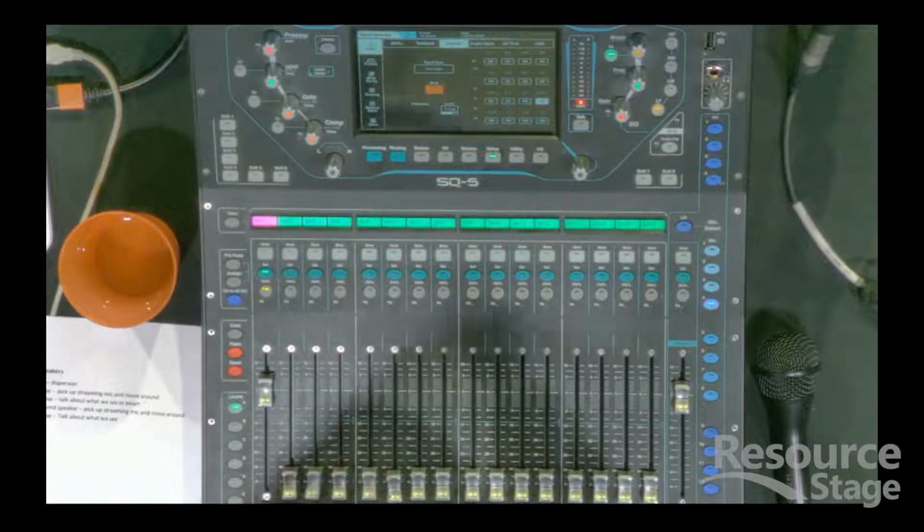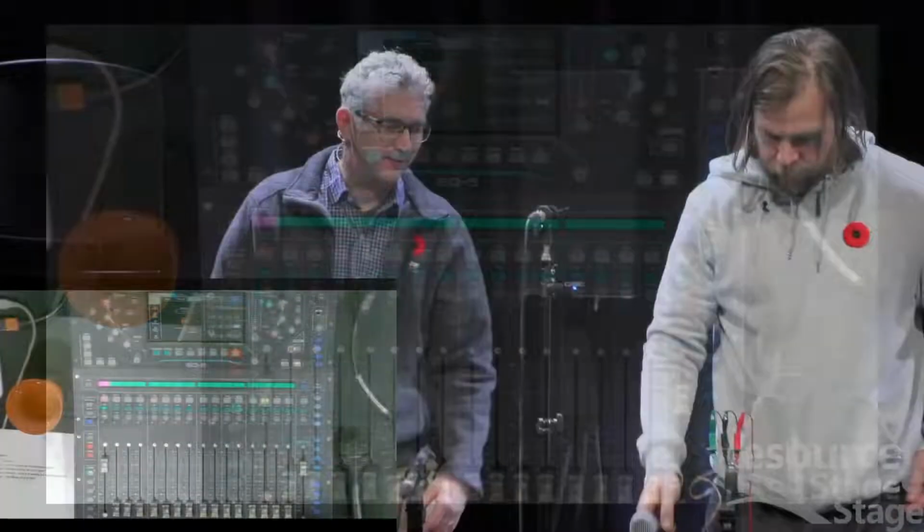So it's important to have the faders operated at or around the 0 mark, so that you've got the most control. You can move the fader a little bit and get a little bit of volume control. If the faders are down halfway, if you've got your gain up too high and your faders are down quite a ways, you move the fader a little bit and it's going to affect the sound quite a bit. That's because the faders are in a logarithmic design, and so that's what affects that.